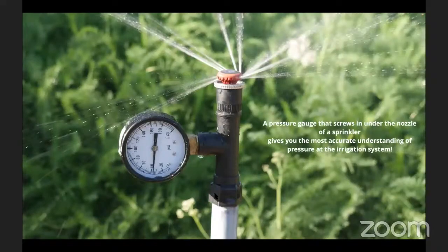The best way, if you're really investing for your whole site, is to test things, and then you will know for your specific irrigation system, and you don't need to worry about whether it is captured by the house or not. If you have an existing sprinkler system with a standard sprinkler nozzle, you can get a pressure gauge where you quickly unscrew your sprinkler nozzle, this part, and then screw on this gauge, which has a little T-piece right where the sprinkler nozzle connected, and that'll give you an accurate pressure right at your actual sprinkler.